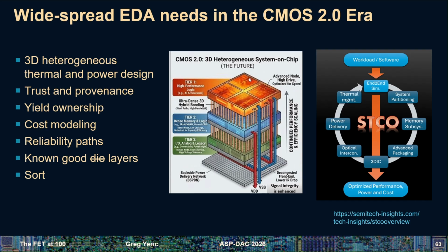When you have one layer, you can put a gigantic piece of metal as a package on the top for a heat sink and pull the heat out. But a chip in the middle is not going to have that advantage. It's got to communicate heat through another layer. That's a problem. Getting power through layers to other layers, big problem.